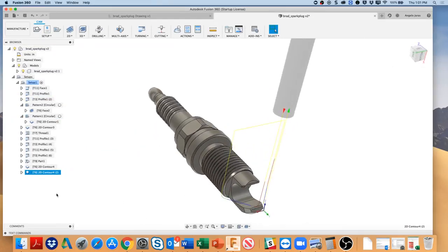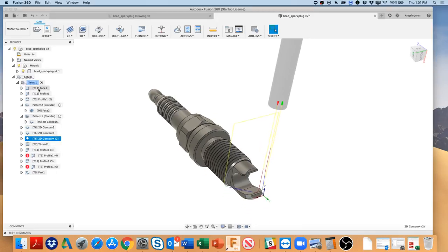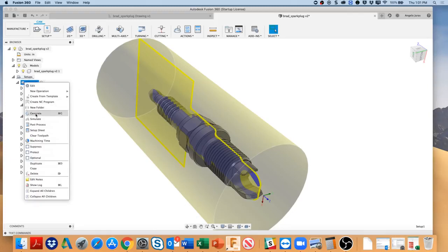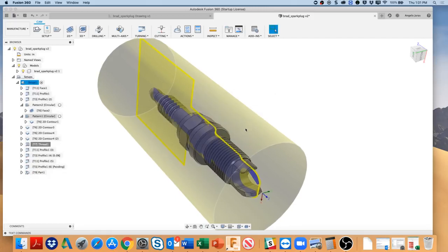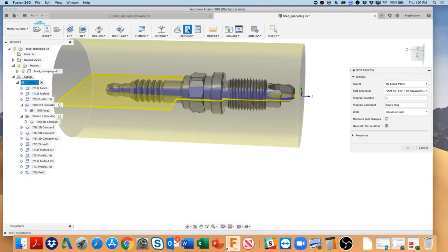And it's machining those edges. So now what I'm going to do, I'm going to drag this guy. I'll put that up here, and we'll move this guy also here. So there's that, that, and that. I will regenerate the ones that got dirty. I'll hit no over here. And then now the part's done, I need to post-process. And I already have my Haas post set, and I'm going to hit OK.